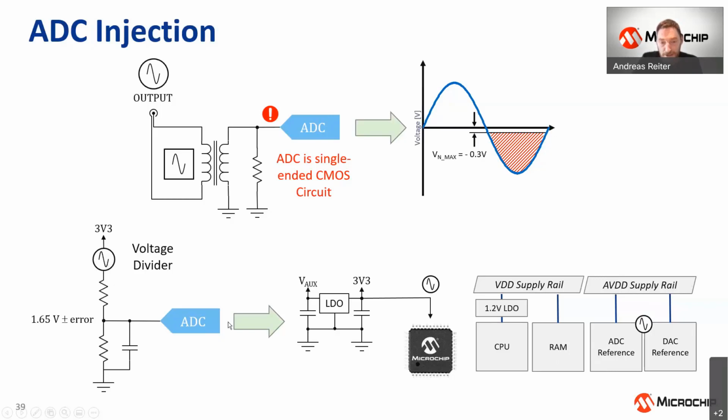So the error injection you're trying to achieve is actually not working that well, because it comes in with magnitude and phase delay, but it is coming in, and so that means that that error signal suddenly starts to influence our internal analog references as well as the feedback signal we are trying to oversample. So the outcome is undefined. It could be anything. So be cautious. Bad idea.